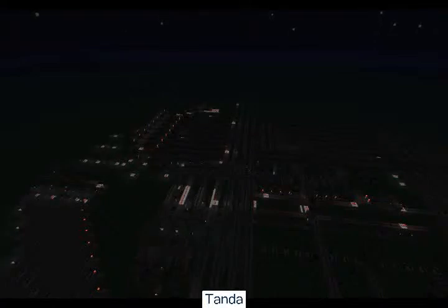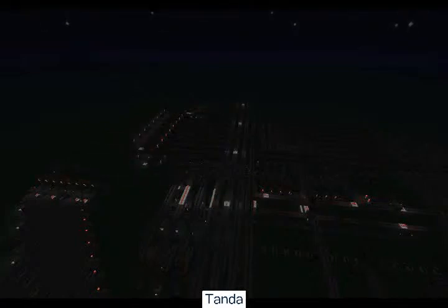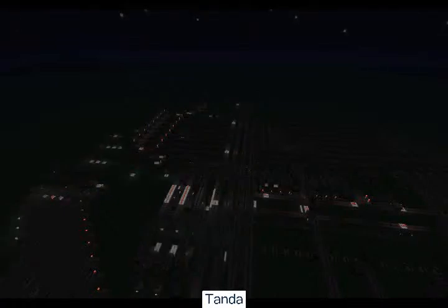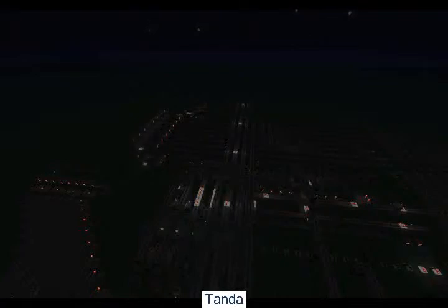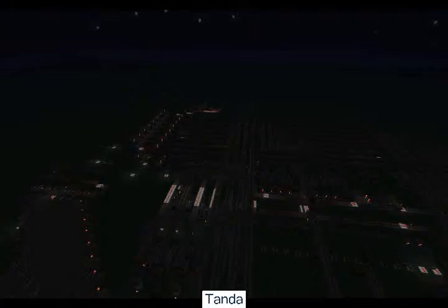Couple of things to point out while it's running. You may see that around the center of the screen it's kind of hidden by 4 bars that go off into the distance, but the thing just below that, which just changed there, is actually a program counter, and what that is literally doing on every clock cycle is just adding 1 to its number, allowing me to access the next section of memory over to the left.